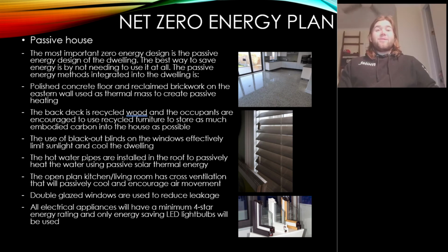Now, the net zero energy design plan. The main focus of this design plan is passive house energy reduction. The easiest way to save energy is if you don't need to use it at all. The main way this will be accomplished is by using polished concrete floors and brickwork on the outside as thermal mass, which will collect energy and heat during the day and emit it at night